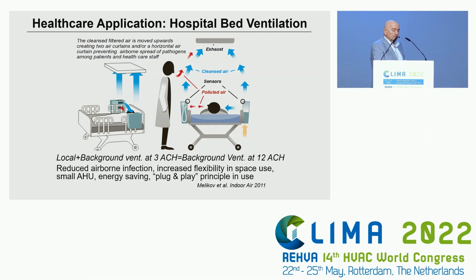Our results show that this local bed ventilation combined with background ventilation at only 3 exchanges per hour provides the same exposure as if we try to ventilate the room with background ventilation at 12 exchanges per hour, 4 times more. A huge difference.